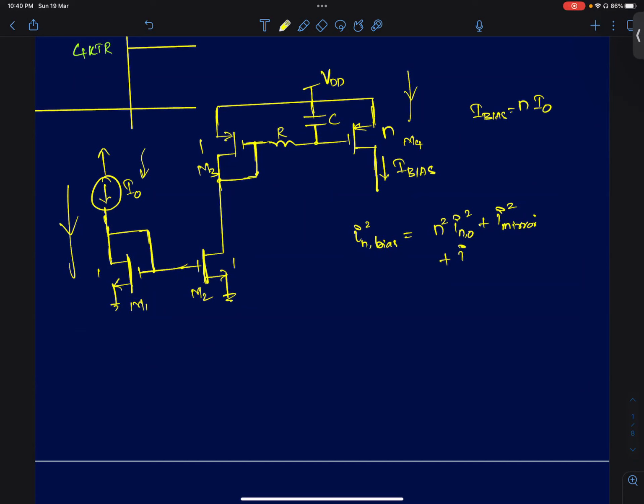And the noise of that current source and also the noise of all these mirroring transistors will all get amplified by the mirroring ratio 1:N here, right? So this is just a 1:1 current mirror. So if I'm injecting a current I0 here, I'll get the same current I0 here as well. And at the output, I'm going to get N times I0. Okay. So this current may be going as a biasing current for some circuit. So I'm interested in minimizing the noise of the biasing current.